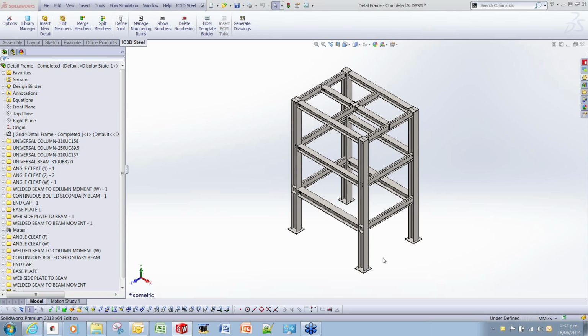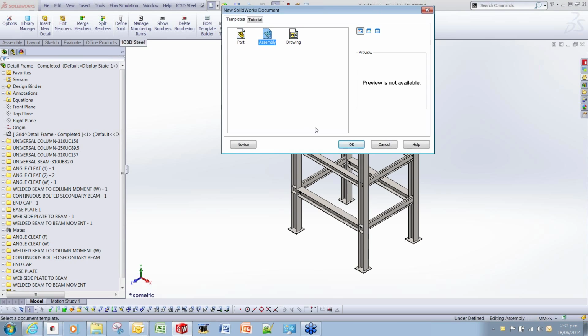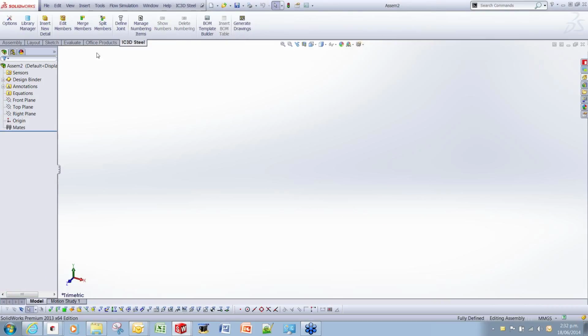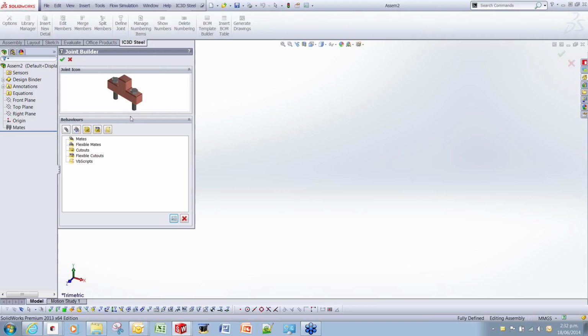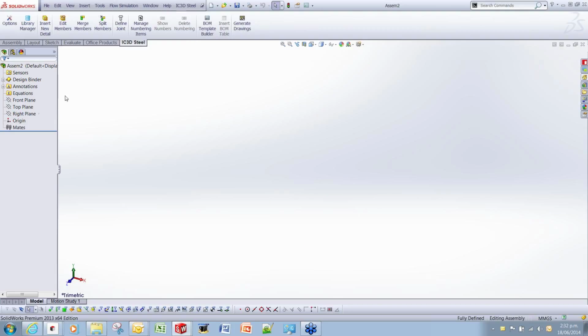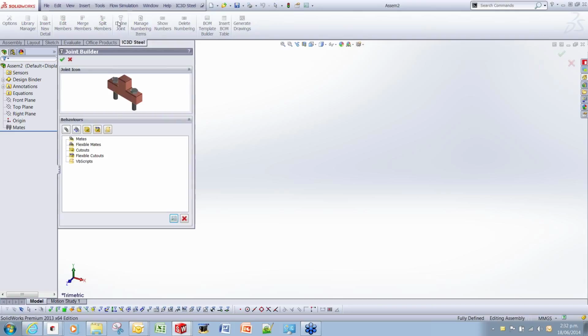Can you define your own joints? Yes, we can actually create your own connections. There is a tool in here where we can define various parameters for a connection. We can create a plate connection, for example, if you have an ad hoc situation. On a lot of jobs you have maybe a horrible connection that's a beast which has lots of things going into it. We can create them in here using these tools, where there's a simple workflow for setting them up.